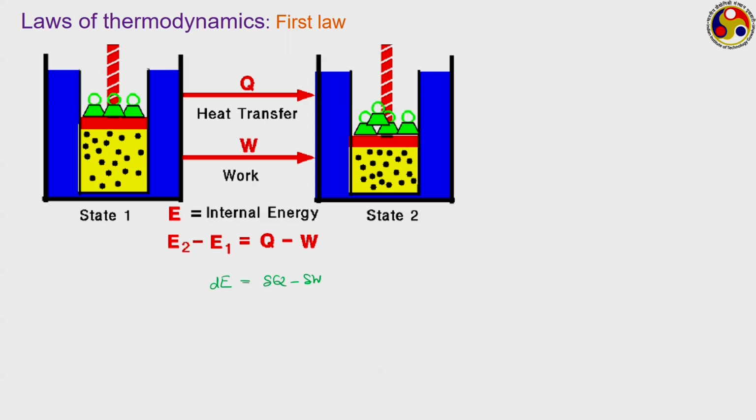And this is during a particular process. If we want to analyze a system, then we have to do this for an entire system and sum all of them up. Think about a particular cycle, let us plot that on a property diagram. Let us say we take a PV diagram. So, we pick up any standard process. Let us say our process initially starts with a compression process from point 1 to point 2, which is at a much higher pressure and low volume. Then we have a constant pressure, that is isobaric expansion process, during which pressure remains constant and volume increases to 3, and then we have another process during which the system comes back from 3 to 1.